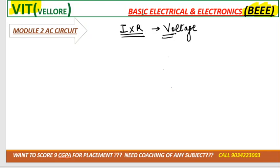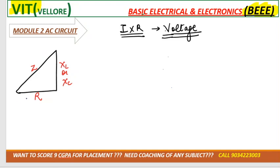It will become voltage, right? According to Ohm's law, V is equal to IR. Now we'll draw the impedance triangle and multiply by current, then we'll get the voltage triangle, right? Here it was R, XL or XC, and Z. So here we can multiply current: I into R, I into XL, I into XC, and I into Z, right? So this will become a voltage triangle.